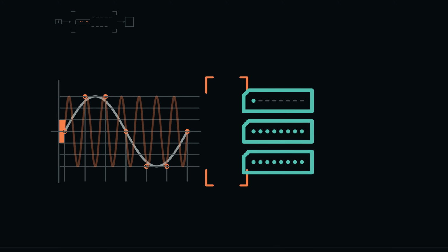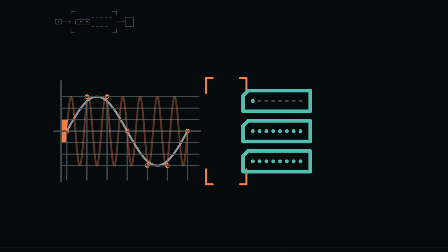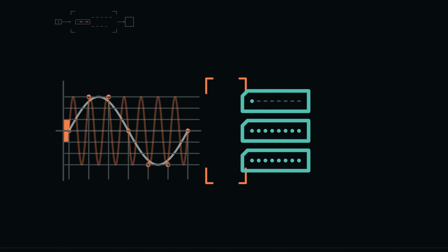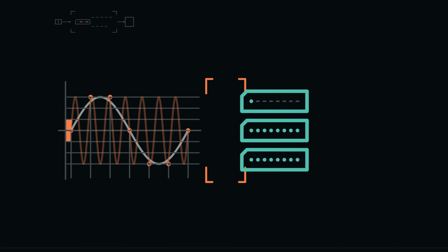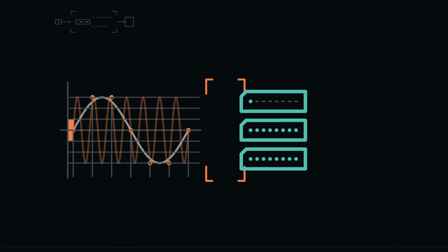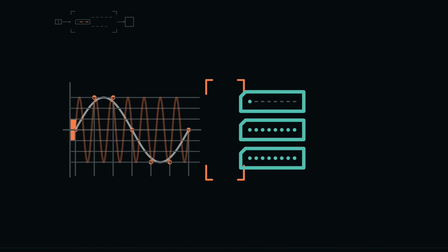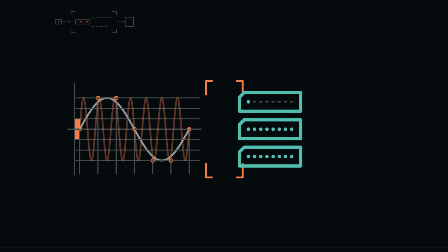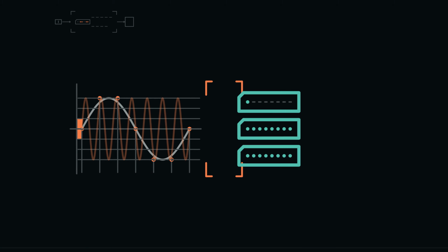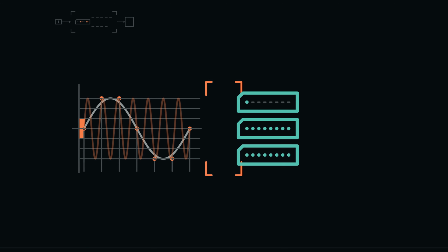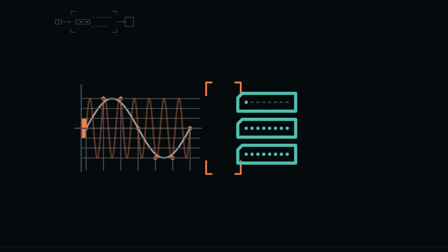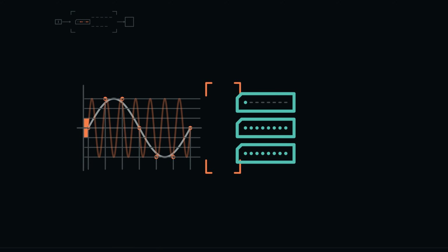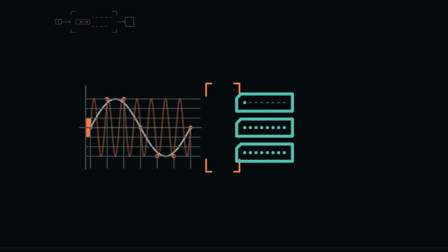The outward path uses a digital to analog converter to map codes to physical output levels over time. A simple converter may hold each requested level until the next sample, producing a stepped waveform. A reconstruction filter can smooth the high-frequency components introduced by those steps and recover an intended band-limited signal within stated limits. The output is a new physical signal constrained by the codes, timing, converter, and filter. It is not the original input emerging unchanged.